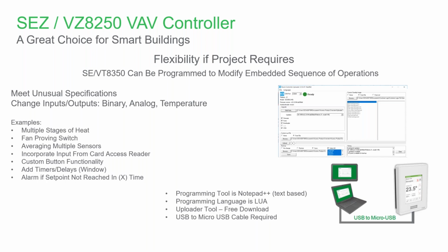And this is the one thing that is very unique about this device and all of our 8000 series. We call them a room controller specifically because they're not a thermostat. They are actually a miniature controller. They've been specifically built with firmware in them to do a specific function. But if you don't like that function, or you need to, what I refer to as mutate that function, they also have the capability to have custom programming put in them.